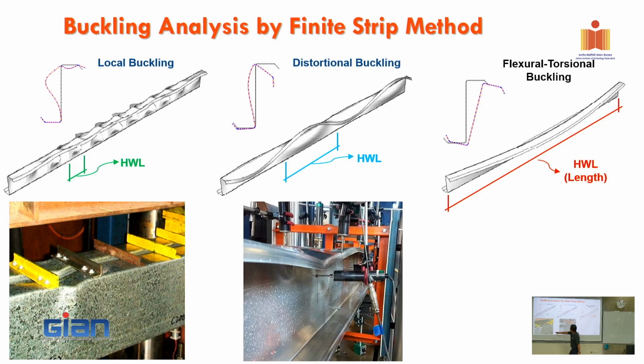This is the half-wavelength. You see that? So I put that one. The spacing is not random. I have to calculate the local buckling half-wavelength, and I have to put the distance here smaller than the half-wavelength of local buckling. So I force that section to fail in local buckling. Okay, so this is why I did the test in local buckling a long time ago.